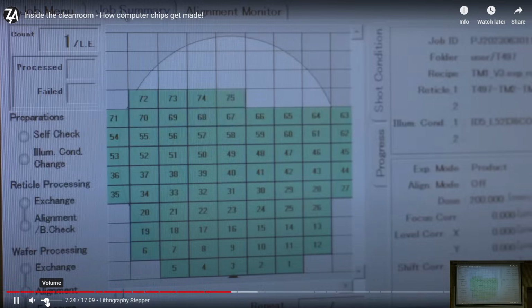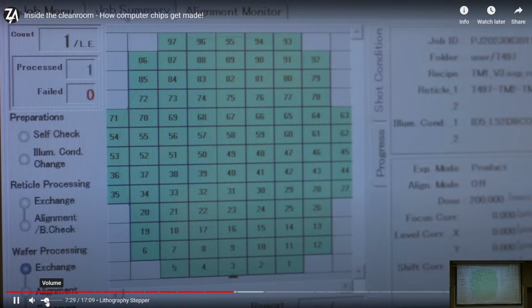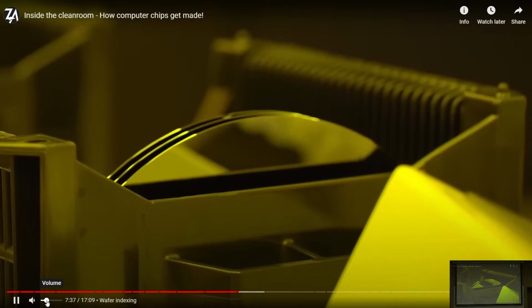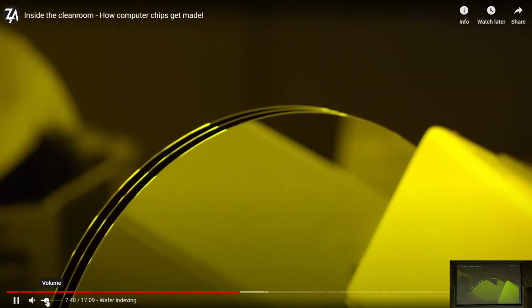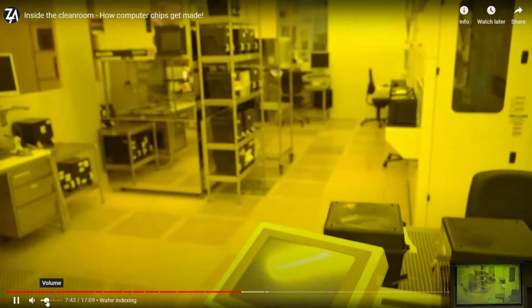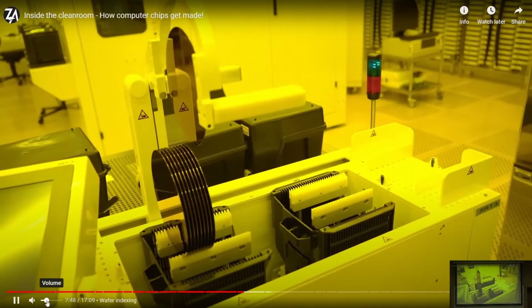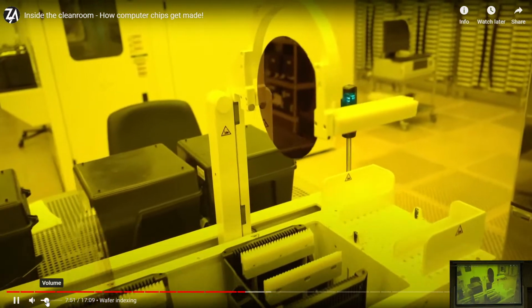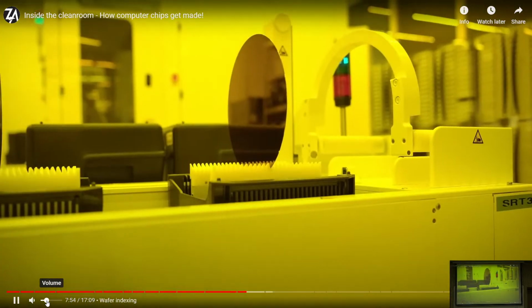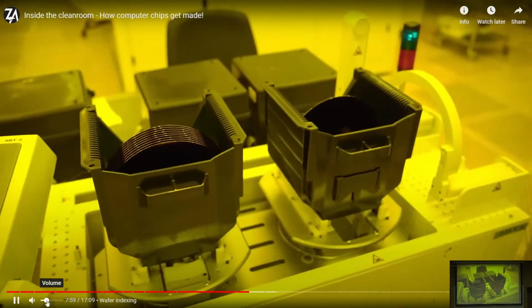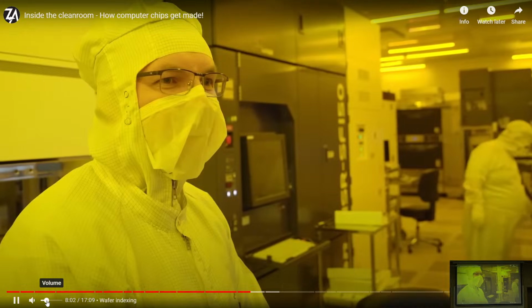Yeah. And over there we have, as I said, the DUV stepper, a step-scanning system that we use for our smallest structures, especially for the critical layers. That's what this tool is for. So I just saw the wafers rotating. Why is that? The wafers have a notch which corresponds to the wafer crystal orientation, to always align the wafer and expose or process it inside the tool in the same way. Wow. Kind of a simple system like this, just a small line, and the machine finds the line. Yeah, exactly.